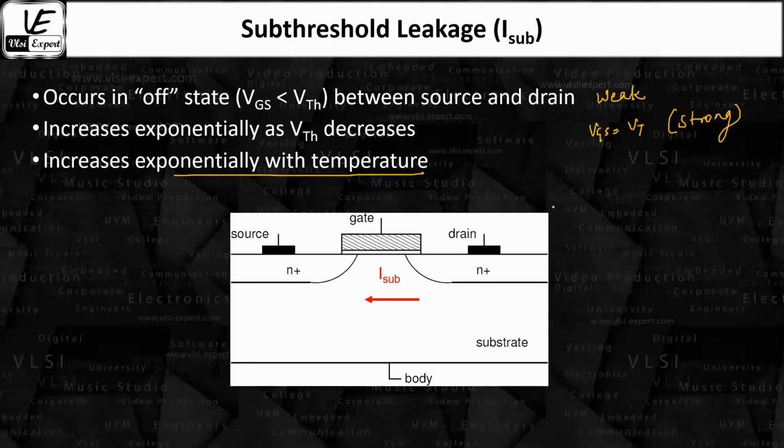Okay, so we can see this is the MOS structure, and in it the subthreshold leakage current flows because the channel length is reduced. Because of that, VDD and VT have to be scaled down, and this reduction of VT means less VGS has to be applied to turn on the device, and the weak inversion region is achieved at a much lower voltage.